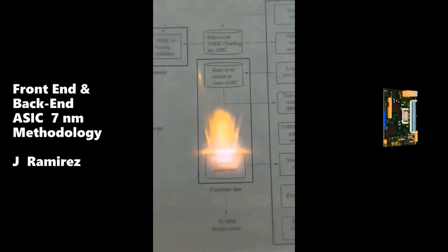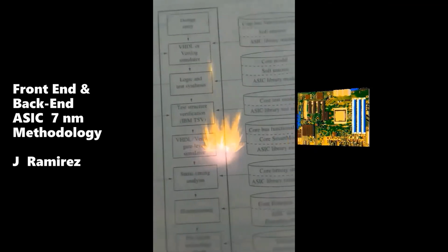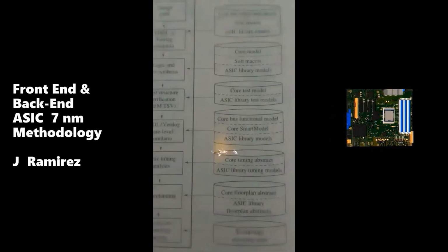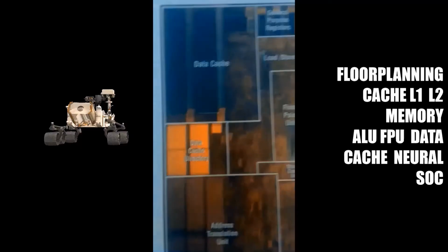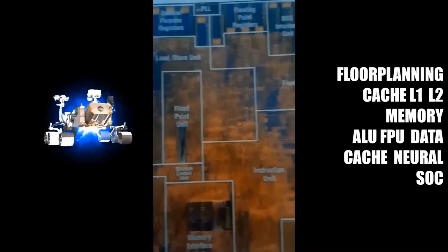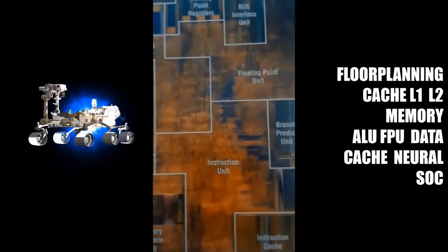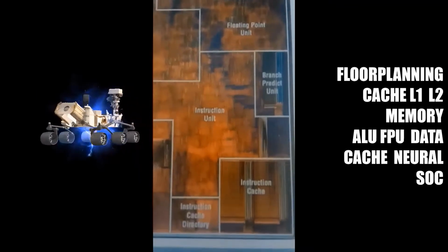Seven, make logic changes, including changes to circuit power levels to fix timing problems. Generate new timing constraints for wiring on the basis of a timing analysis done using the actual clock tree and wire load and RC delay values derived from the final placement. And finally, perform routing.